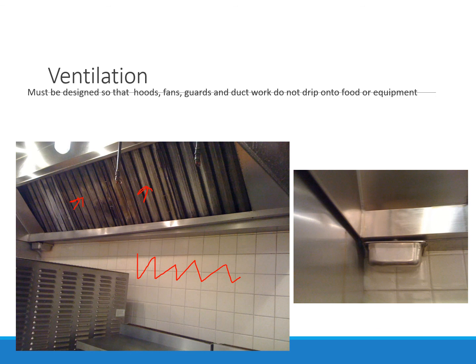grease, everything up there. Now, one thing that you'll notice about the design is that the piece on the bottom right here, where potentially oil could condense on these things or moisture could condense on these things, it runs down into this channel. And if you'll notice, this channel is at an angle. So we've got a large, up here to here, the difference is pretty substantial. So anything that drips in this, that condenses, goes in here and runs down this channel. And it runs all the way down to this end, where there's a hole where it goes into this